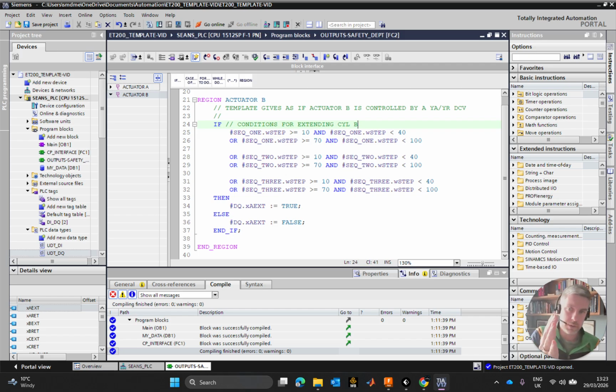The spool stays where it is. There's no spring to kick it back, so it just stays there, and the pressure is maintained through port 4 into the cap end of the cylinder. The only time it retracts is when I give a pulse to terminal 12 of the solenoid, and the spool shifts over and lets air out of port 2 of the direction control valve, and shifts it back.